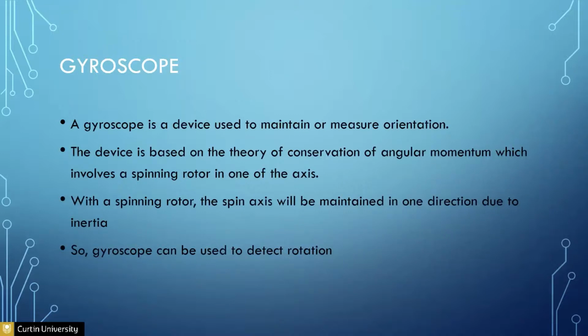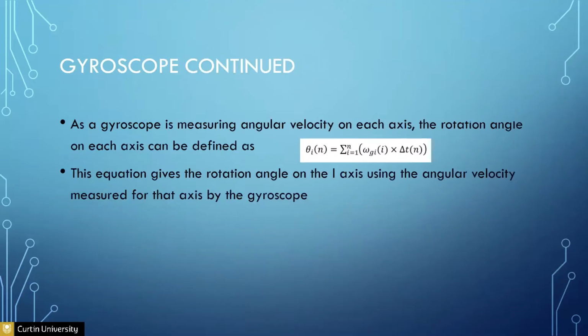So because we can get these two interesting characteristics from these IMU sensors, and usually in the projects I've been personally involved in, I haven't used the magnetometer that much because it's very prone to electrical interference. Sorry, I mean magnetic interference. So we just use the accelerometer and gyroscope. And the formula that you're seeing here is how we convert the X, Y, Z values from these sensors to actual angular velocity and movement.